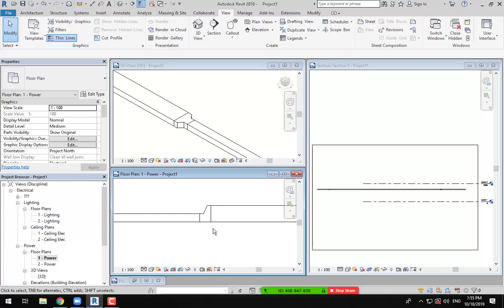So there is a need for this option when you have a defined place, or you are making shop drawings, or you're making construction or installation for cable tray on site, and you have a narrow place and you want to make a constant side for the cable tray beside the wall and reduce the angle from the other side. Okay, understand this?